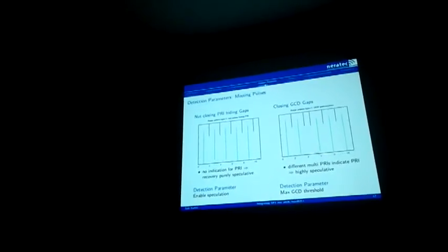The next one is similar to that, but here we could maybe speculate it was a radar because of the following. You see gaps of 1 and you see one gap of 2 missed pulses, meaning you can break it down to some greatest common divisor, and then you need to decide what thresholds you want to enable here to treat this as a radar pattern.